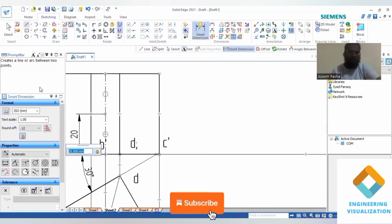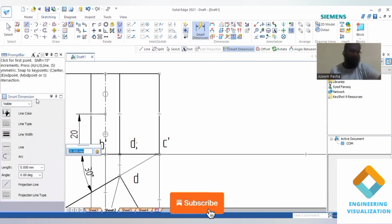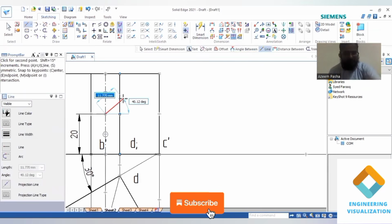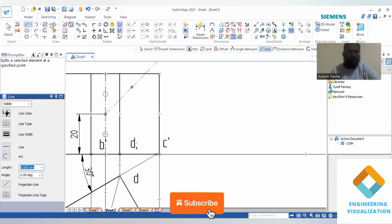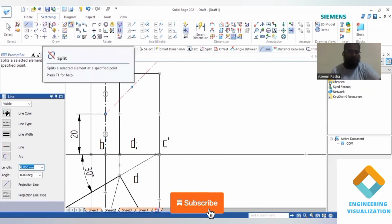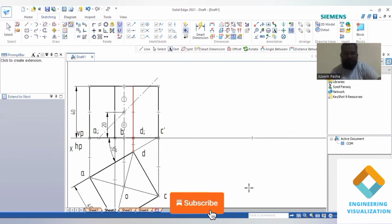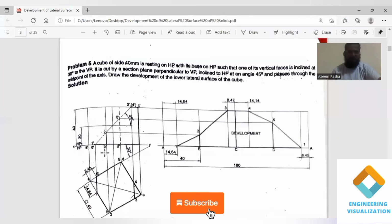Now you take a line, section plane, we have to draw an angle line for an angle of 45 degree here. You can give the angle 45 degree, enter, then you just draw a straight line. So we need to draw an angle line. Now using the extend to next command, we can extend the same section plane downward also. So it is extended. Now I can show the angle. You can see that we have done.